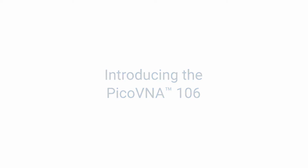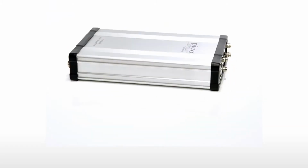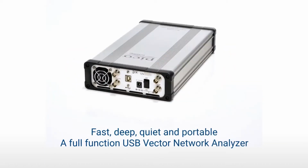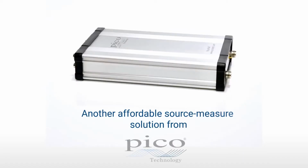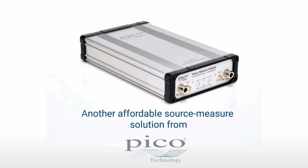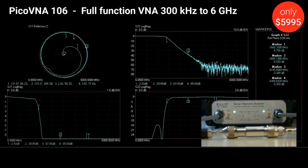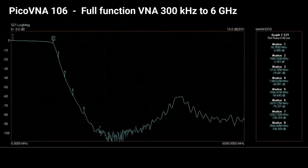Hi, I'm Mark Ashcroft. Let's take a quick run through some of the features and performance of the PicoVNA 106 USB-controlled 6 GHz Vector Network Analyzer. Fast, deep, quiet and portable, the PicoVNA 106, despite its small footprint and its low price, is a full-function 2-port bidirectional VNA, with all the measurement and plot formats that you would expect, and of course, the PC and monitor of your choice. There's nothing left out here. Nominal impedance conversion to 75 ohm, for instance, reference plane shift and embed de-embed are all included,